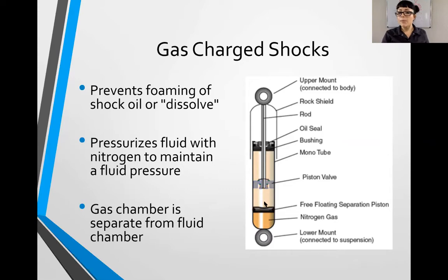Well, if I get air pockets in places I don't want, then those air pockets, air can compress, while fluid cannot. So the air pockets are actually going to make the shocks feel way more squishy than they should. And that can change from side to side. That can change with temperature. We don't want that. So what we do with gas charged shocks is we put a little chamber, and I'm just going to talk about one design. I'm not going to talk about all of them or reservoirs or anything like that, because reservoirs do the same thing. But I'm going to have some sort of chamber somewhere.